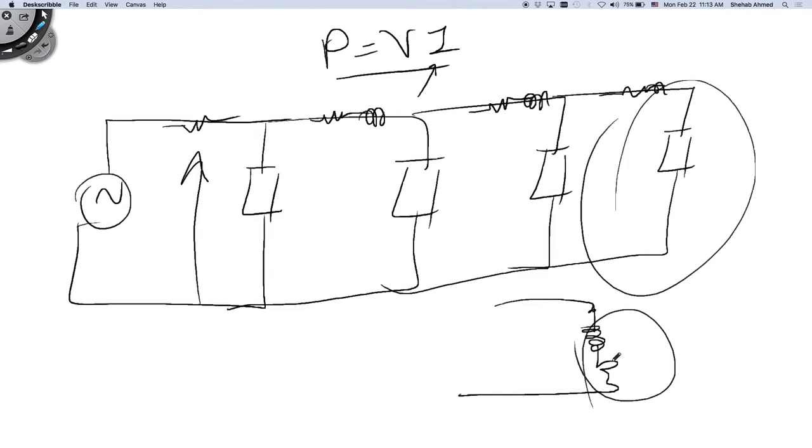Oh, we would love to do that. If the voltage and current are in the same phase, then it looks like I only have resistors in the system, right? Any utility only charges consumers for the real power. Real power is what is dissipated in the resistor. The guy doing this on the bicycle and the guy doing the other side on the bicycle, this is what we call reactive power. That's the analogy for reactive power. It's something that I have to have, otherwise everybody will fall down, in the bicycle analogy. It's something I need to have in the system because of the physics.